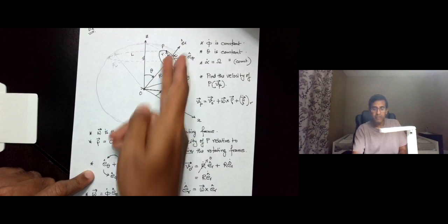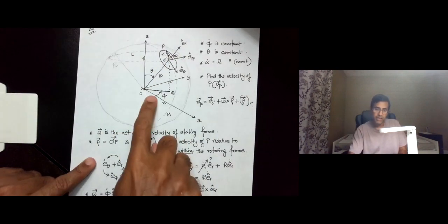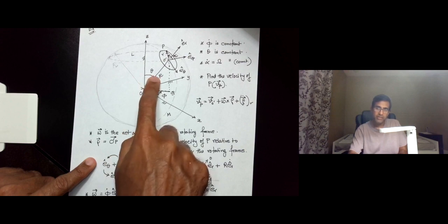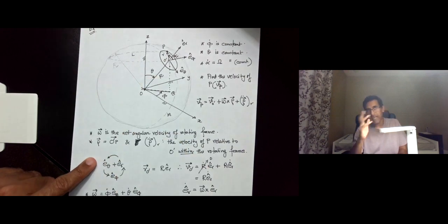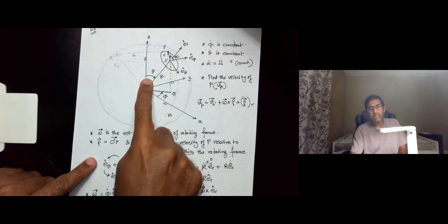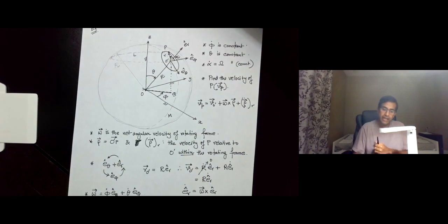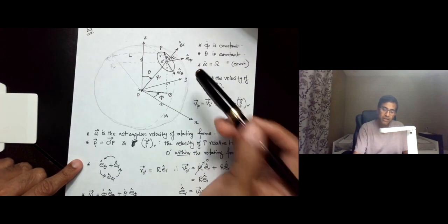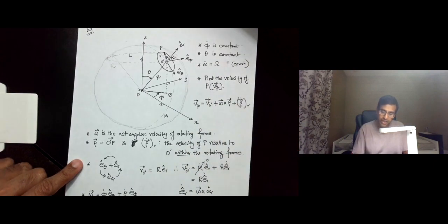That spin of the axis is called the precession, and the gyroscope is maintaining a constant angle theta. So that is basically a precession with a constant nutation angle. This angle theta is often referred to as the nutation angle in gyroscopes, and so in this case we have a precession under constant nutation angle.